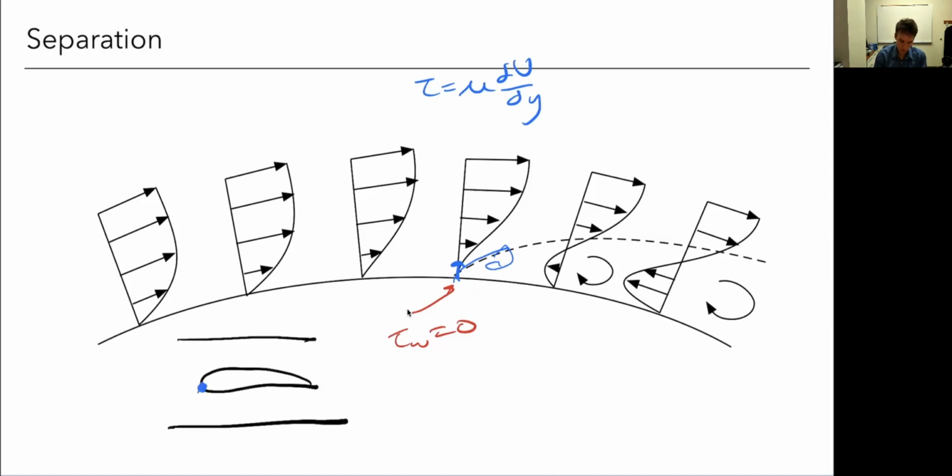Right, and if that's a stagnation point, that's not a problem if I'm outside here of the wing, away from the fuselage, because this is for the wing at least in a very favorable region, so it'll accelerate over, no separation. But if I'm looking at the fluid passing along this fuselage, this is not in a favorable gradient. It's just moving here alongside the fuselage, and then I hit this stagnation point. Well, by definition, then I'm going to separate, right? Because I don't have any favorable gradient anymore. I have no more forward velocity. And so it's going to cause some separation on the fuselage.